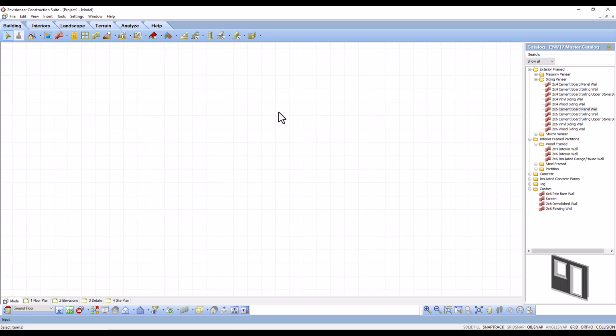When you apply a material in Envisioneer, it copies it across the face of the receiving object. If the material is smaller than the object, it will continuously repeat the material to fill the face of the object. This can have some undesirable effects if the material has a definitive edge that is repeated across the face of the object, making the material appear fake. Once you have the material saved to your computer, you can start to edit it if needed to remove any parts of material that would make it not repeat correctly.